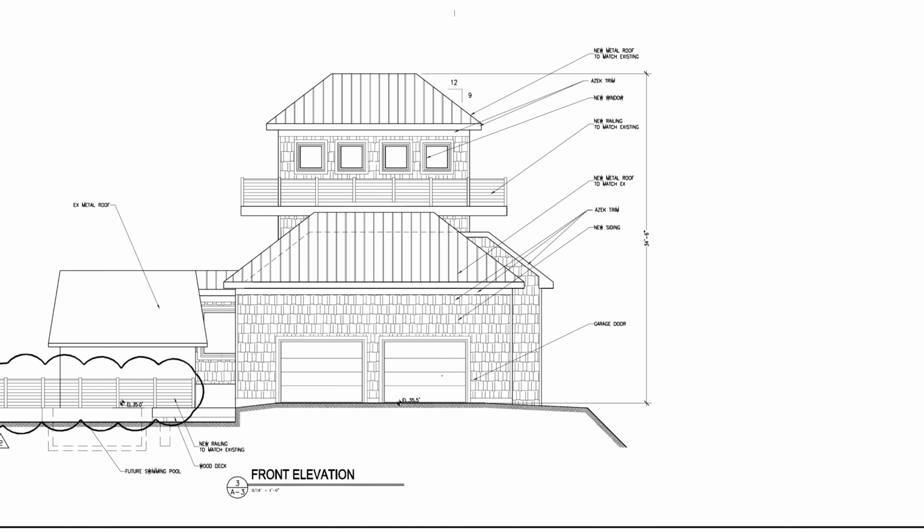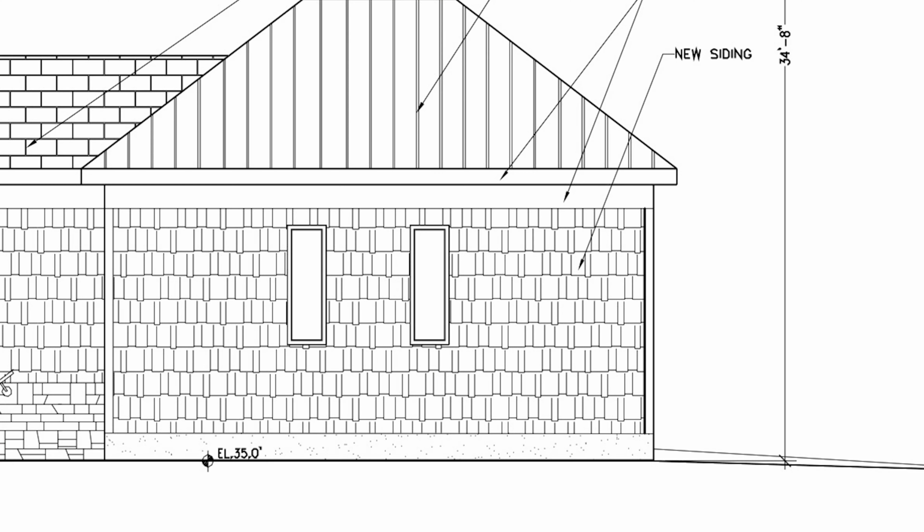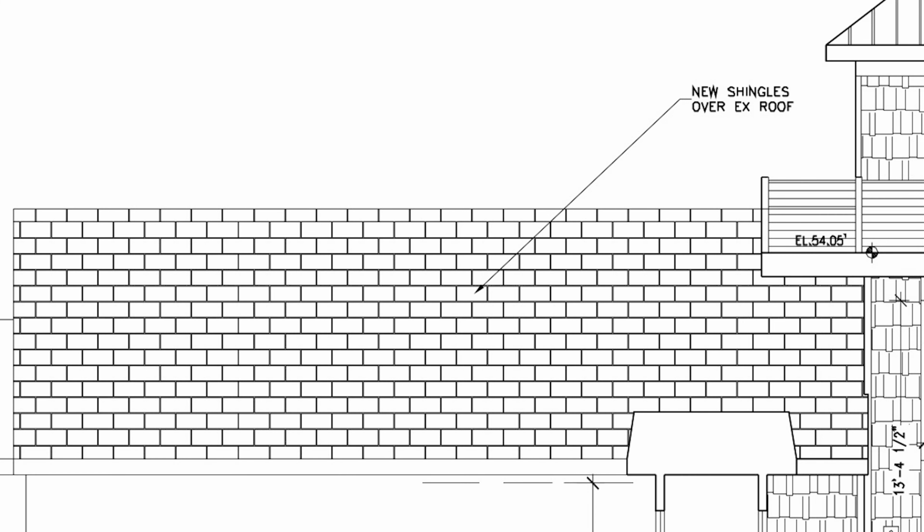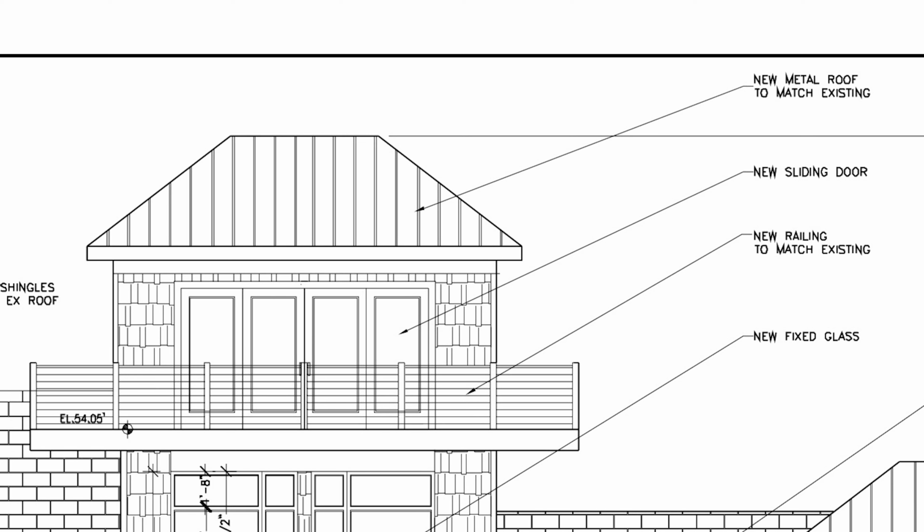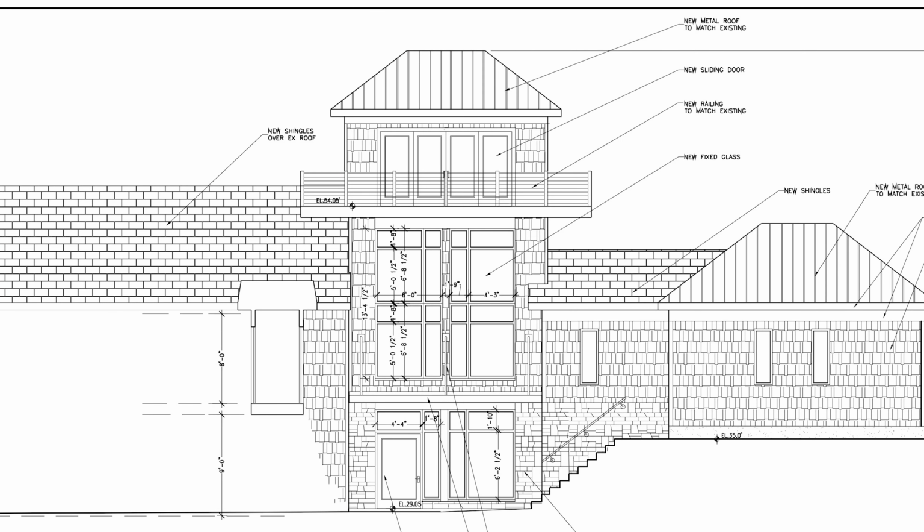For example, the siding was made out of hardyboard. Yeah, we have hardyboard siding, and this shows the roof shingles. And because of the existing portion of the house, we redid the shingles in order to match. This represents siding, and we used cedar impression hardy siding here, asphalt shingles, and then there is also a metal roof. So you can see the different symbols for materials.